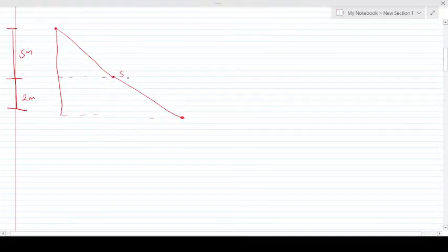So here is the 57.6895. Then we have 89.9061. So this is your pressure diagram. The next thing is to find the force. In finding the force, you need to find the area of the pressure diagram. So we can put this into simple shapes so that we're able to find it.